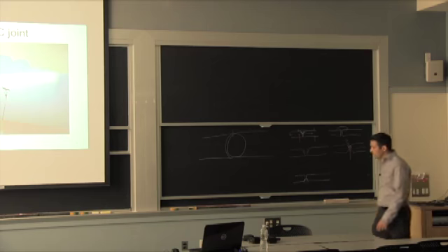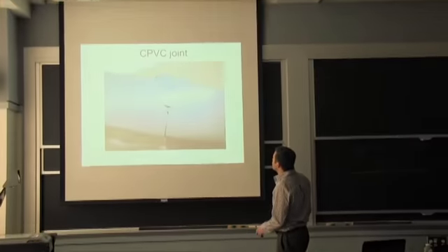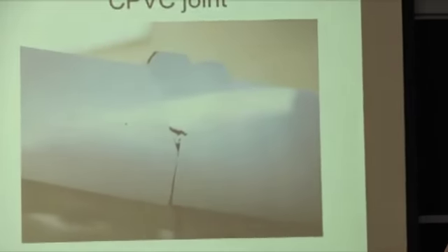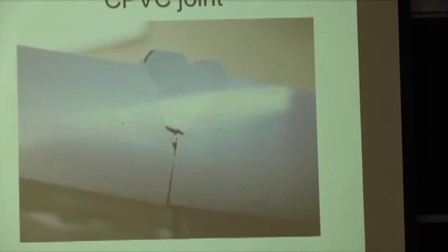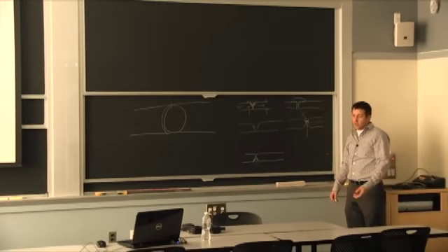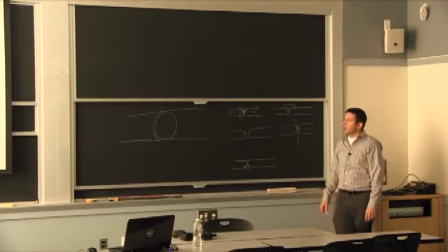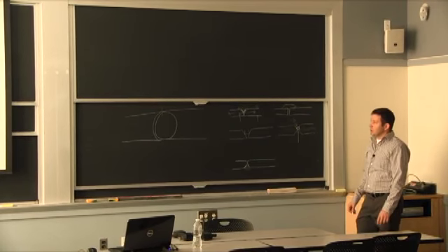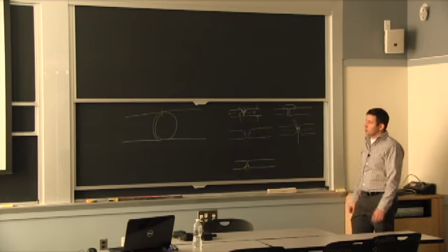And you know, in this image, we even see a porosity, which is a hole. But it wouldn't be uncommon. You don't expect the root of the weld to be the strongest part, and this is one of the reasons. The other reason is that it's really a stress riser, and it's a location where you have shrinkage forces. There's so much going on in welding that you can't expect all of it to be perfect, especially the root.